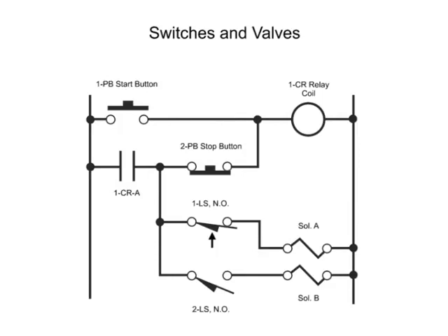A holding relay is a necessary part of this circuit. Its coil is shown as a circle marked 1CR. Holding relays typically operate one or more relay contact sets. In this diagram, the holding relay operates one set of contacts. The contacts are depicted as normally open. As with switches, they can also be manufactured as normally closed, with a slash mark depicting the normally closed state.